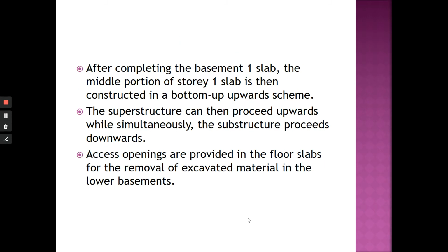After completing the basement 1 slab, the middle portion of story 1 slab is then constructed bottom up. So basically they leave a hollow on the slab.